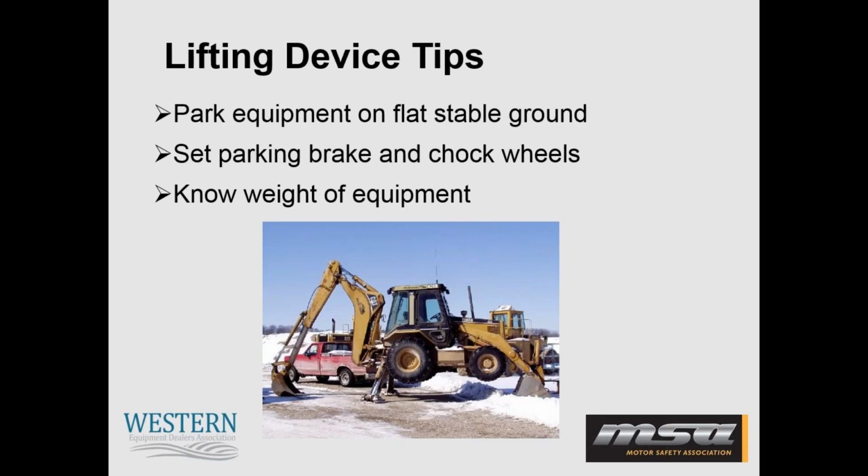I'm going to have a few slides here with some lifting device tips. And when I look at this diagram, would you work under this load? I wouldn't either. And as I said, I'll have some different lifting device tips. So if possible, try to park your equipment on flat, stable ground. Again, if your equipment breaks down, you don't really have a choice sometimes where it breaks down. But if you do have the availability to park on flat, stable ground, that's always the best practice. And then you're going to want to set the parking brake and chock the wheels.